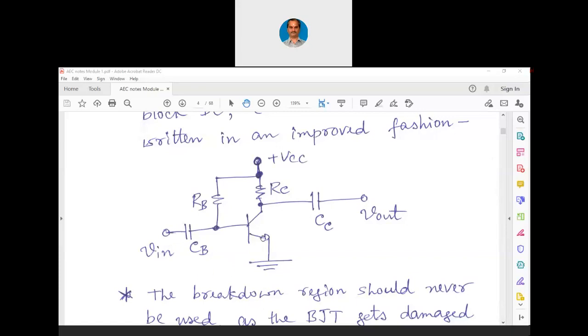Now we need an amplifier which can amplify my signal to a larger volume. Look at this particular circuitry. At Vin, my microphone is there. Think that way. This particular amplifier circuit is already there inside my laptop. At Vin, when I speak, my speech will be hardly around a few millivolts. If I speak at an even lesser volume, it may be microvolts also. It is hardly a few millivolts, because it is my vibrating vocal cord that produces the voice.